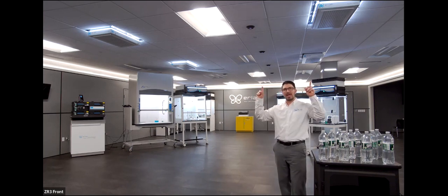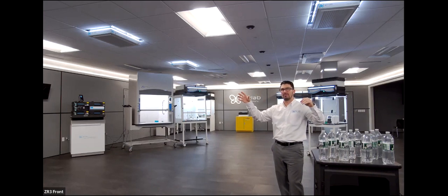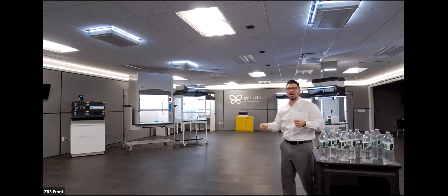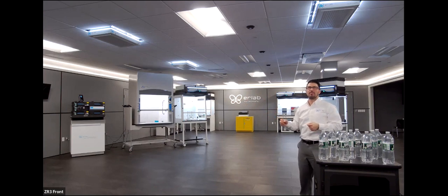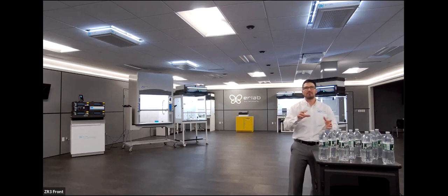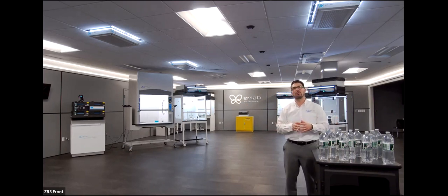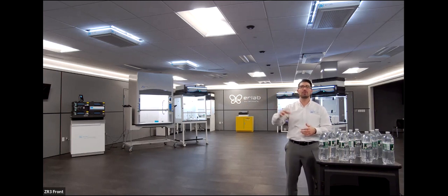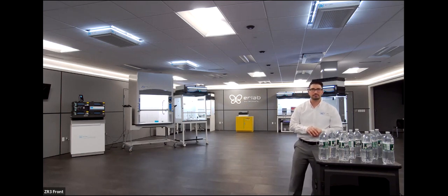And then for the Halos, it will detect any type of fan speed reduction. It will detect any type of spikes in volatile organic compounds, VOCs, or acids when we talk about laboratories. And then that light will pulse, followed by an audible. You can see the light pulsing on that little command module there. And then we have what's known as eGuard. It's a web-based portal where you can actually go in and take data shots of exactly what's going on with every one of your products. And you can control all the products through that system as well.